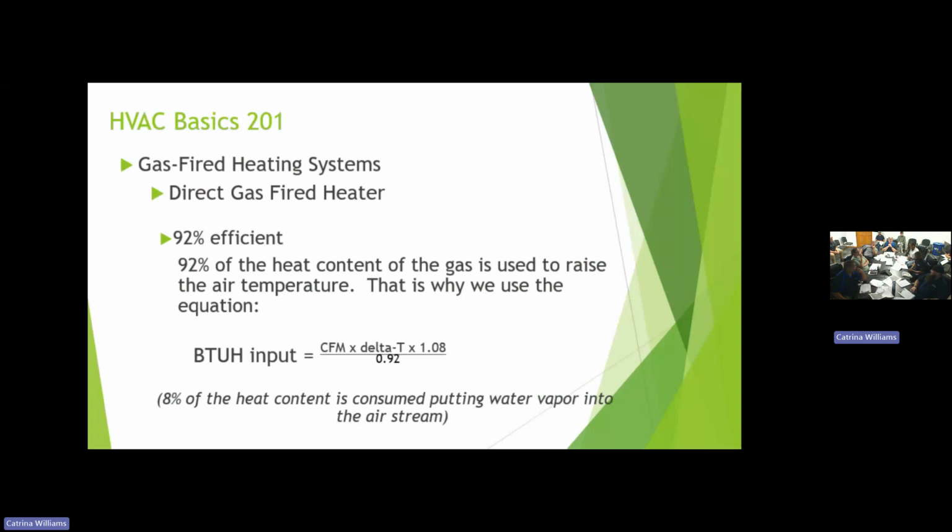Don't get me wrong, you're not the first person. I remember when I was in sales years ago, some guy had a unit delivered to him, and he called me up and said, well, I got this unit, but I don't know where the chimney is. And I said, well, you don't need one on this unit, it's direct fired. He said, huh? I said, well, there are products of combustion in the airstream, but it's safe. He said, not in my building. People still fight that because they just don't trust it.